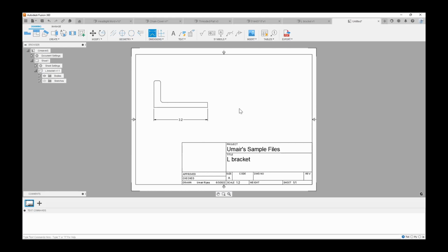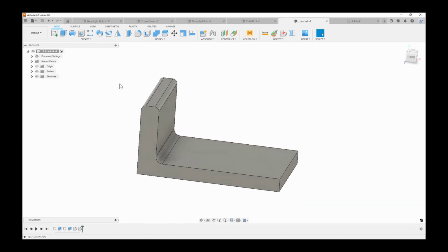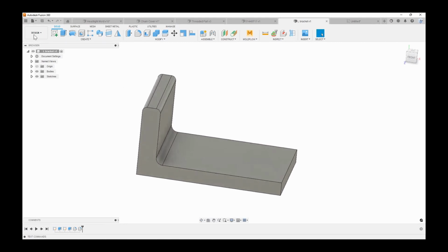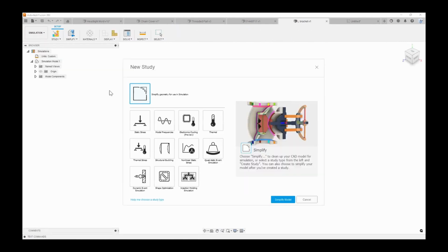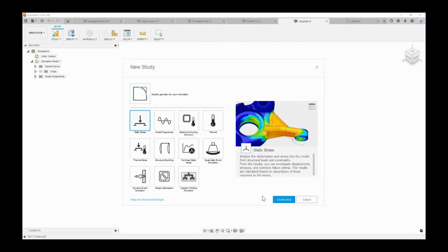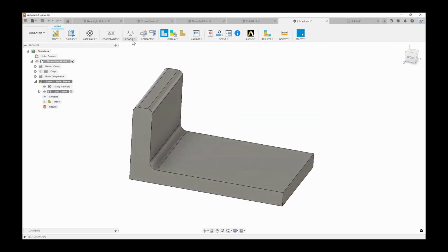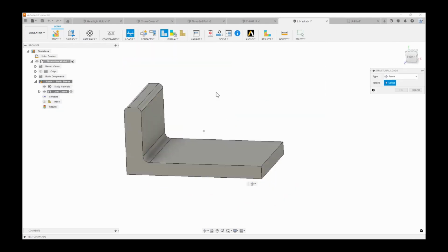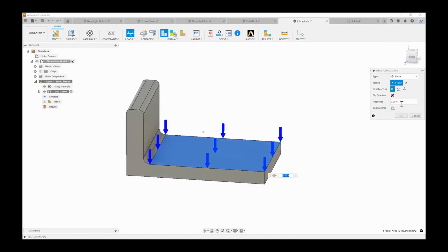The other thing I would like to point out is, like I said earlier, we want to make sure that these parts are going to work and they're going to be used to the best of their ability, right? So you quickly, even doing a quick simulation just to make sure, hey, can it handle a certain load, right? So I can quickly create static analysis here, put up a quick load, say, hey, I would like to make sure that this particular area can handle this much of load, right?